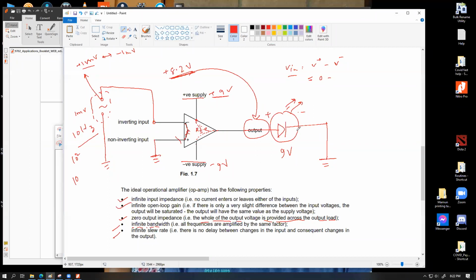So what it's saying is that if the input side frequency variation is extremely large, the ideal op-amp is capable to give an output with the exact same frequency. So it would not have any problem to handle any amount of frequency of alternating voltage to reflect onto the output side, which is not practical because these are made from physical components.